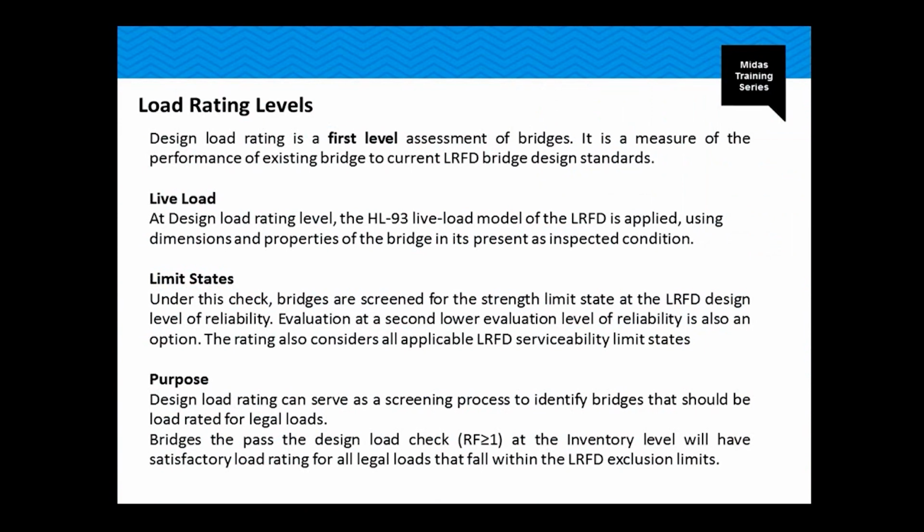It is the measure of the performance of the existing bridge to the current LRFD bridge design standards. Plain simple. The live load at the design level, the HL93 load, is used, using dimensions and properties of the bridge in its present inspection condition. The limit states in this case, the bridge is screened for strength limit state as per LRFD.